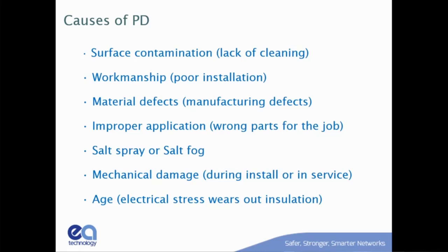And really anywhere you've got guys out in the field doing work, manipulating stuff, responsible for maintaining the field stresses, like a cable joint, where the guy's got to strip it back, make sure he gets all the semiconductor off, not nick the insulation, and put everything in right. That's the most likely, and usually those are done in a trench or God knows where under less than ideal conditions. That's the most likely scenario. I'll touch on that a little bit more.